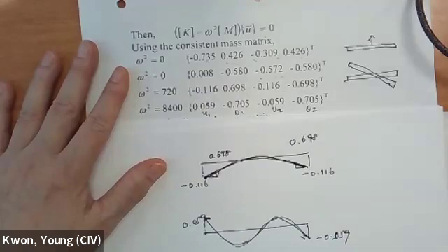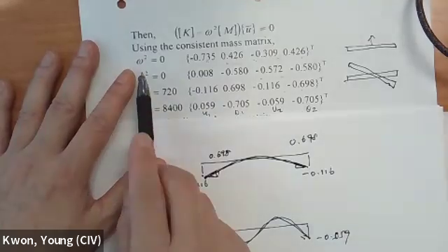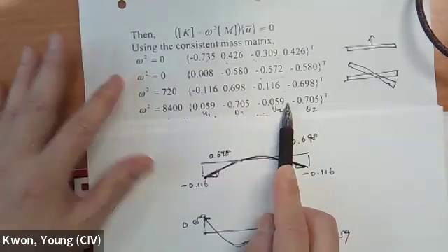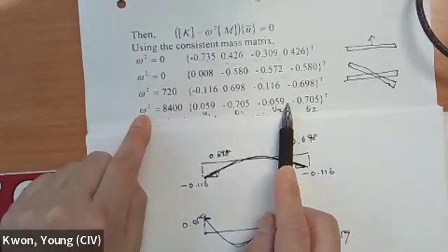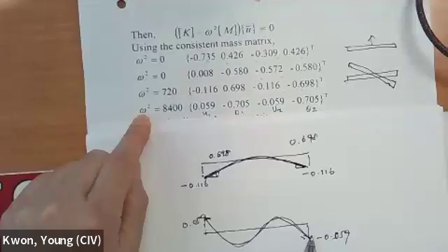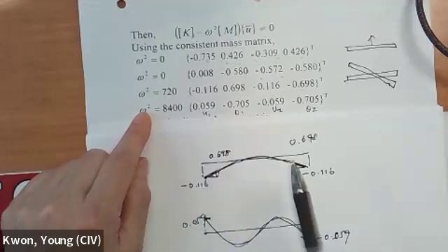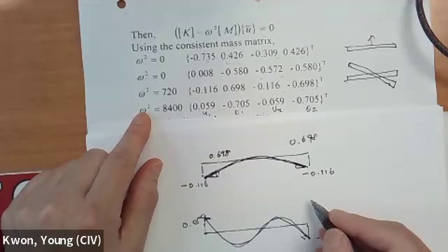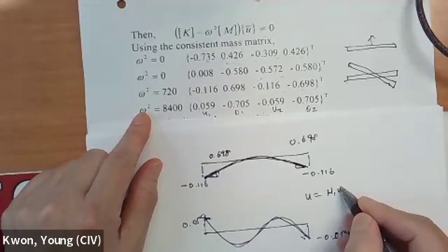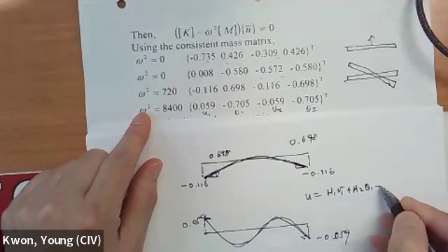Okay, so that's going to be the second mode shape. You were inferring, since omega 2 wasn't 0, that it's not going to be a straight line. If this happened to be the zero omega value, then it should be a straight line, because that's going to be rigid body motion. But this is non-rigid body motion, so what you need to do is just plug into this expression. That's how you get it plotted.